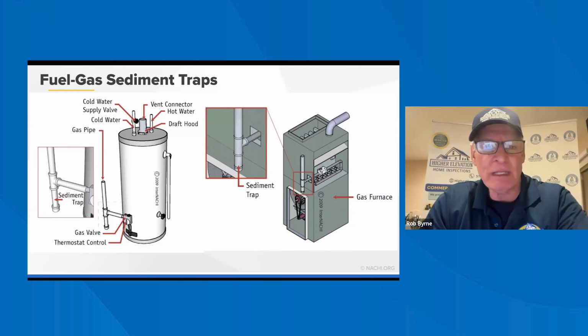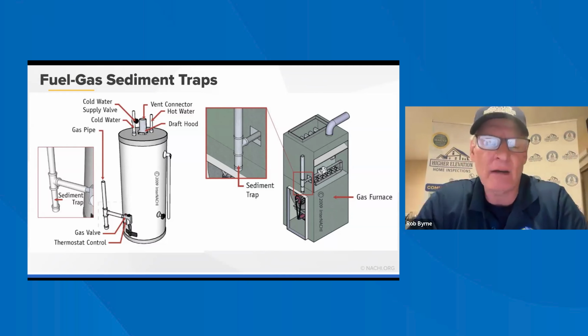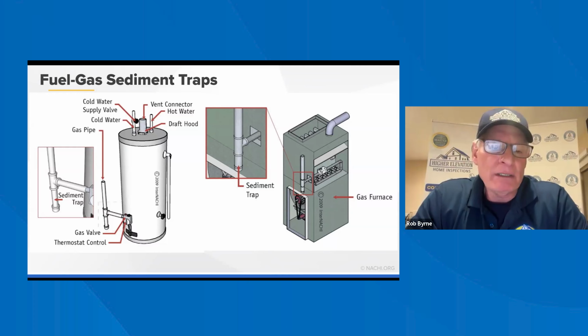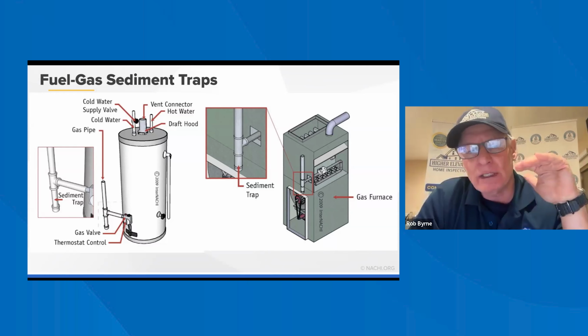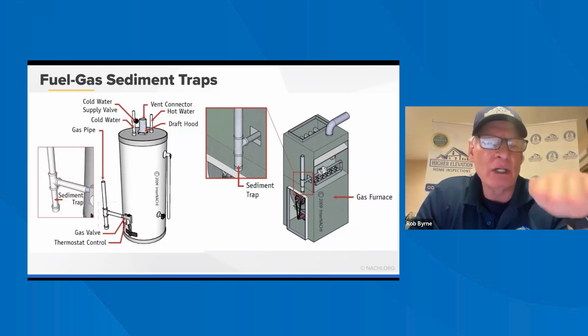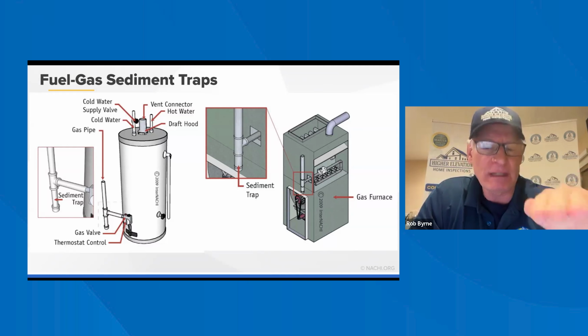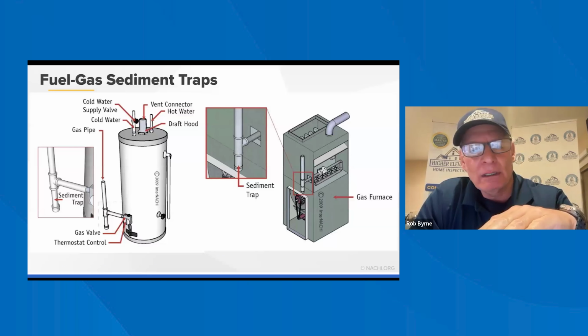You have to have that space underneath it. A lot of times they just screw it down to the bottom and they don't have that. It's not right. One of the biggest challenges we're seeing is that when you replace a water heater, a lot of times the water heater is taller than the old one. And what happens is that where that vent connector is, it's going to vent out into the chimney. You'll see it back pitched.